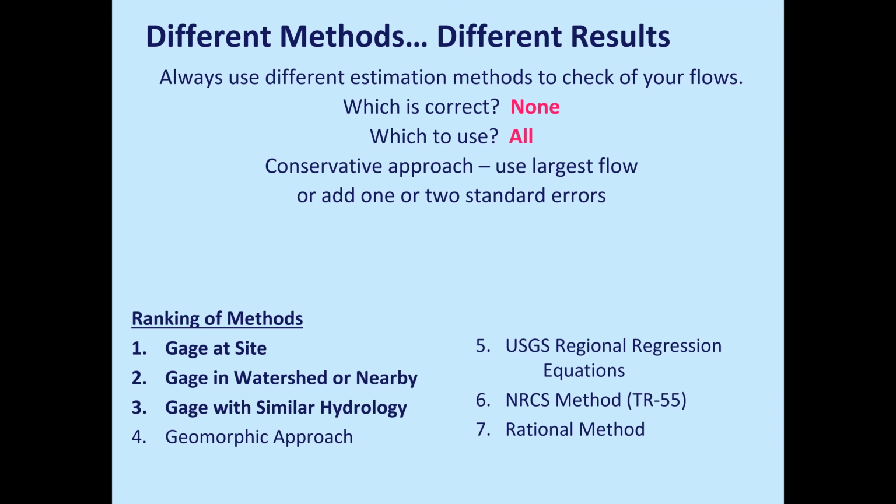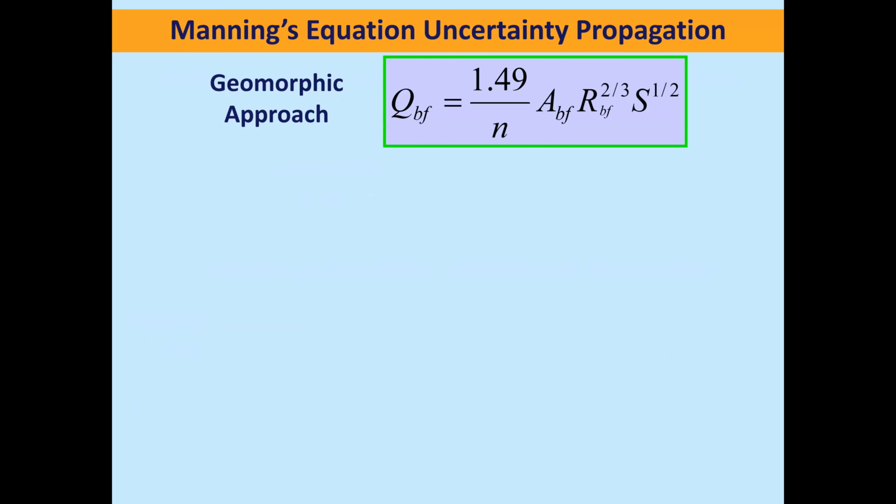Conservative approach, but also keep in mind, if you go too large, you're also potentially wasting resources that could be used on a different crossing. So try to come up with a good medium that also has you feeling okay with the result. It takes some work and iteration for sure. And finally, just develop local prediction techniques, get to know those local watersheds, what's driving them, and collect local flow data if you can, for sure.